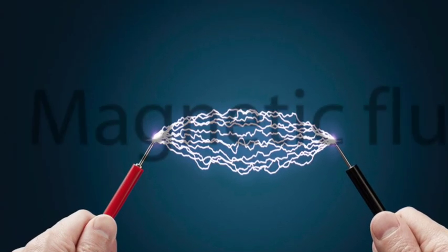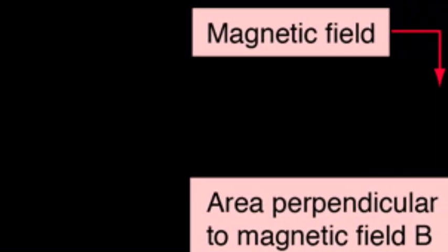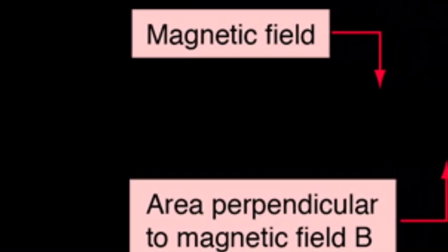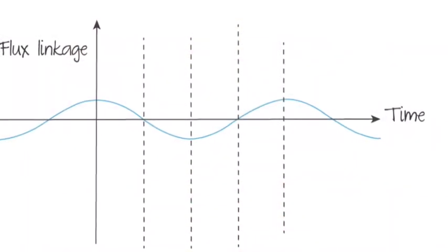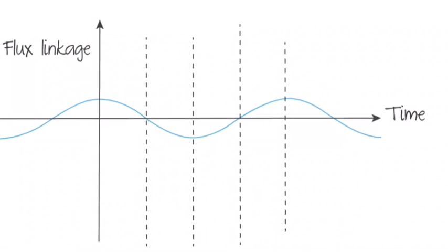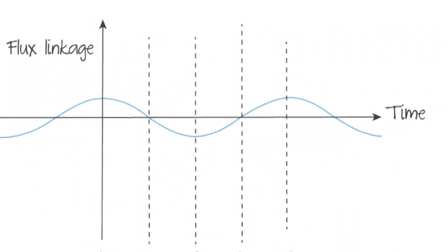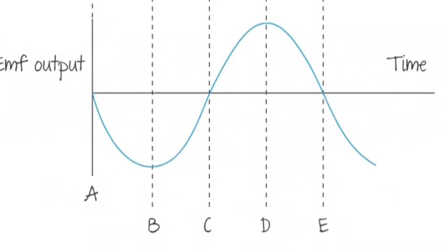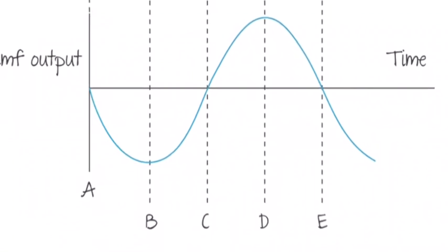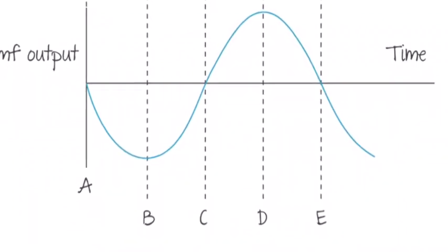To generate electricity, we need to rotate a coil of wire within a permanent magnetic field. As the flux is given by NBA cos theta, the only variable changing the flux is the angle, resulting in a flux linkage times time graph in the shape of a cos graph. And as the induced EMF is only generated when there is a change in the flux, only in the fragments where there is a tangent not equal to zero, EMF will be induced, resulting in a negative sinusoidal variation, as we could derive when placing the flux formula into the EMF induced formula, as shown right now.